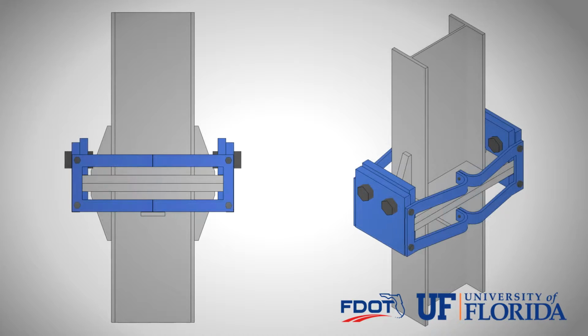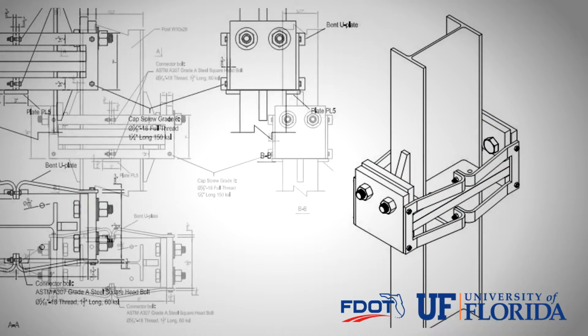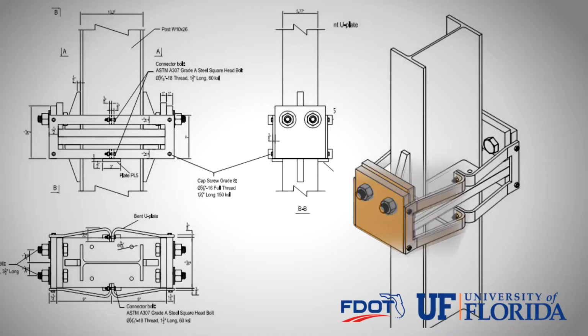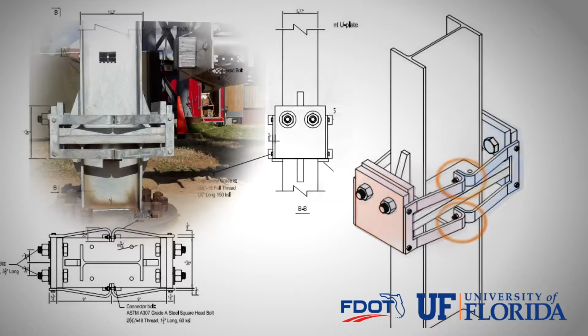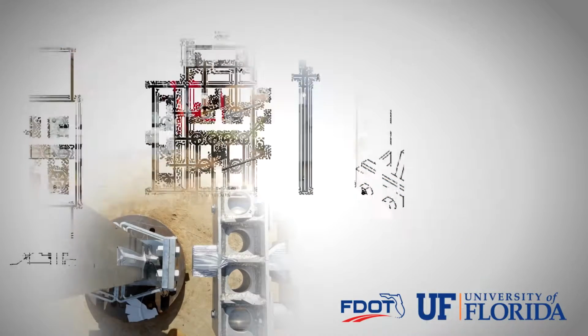The shear control moment collar is designed to clamp down on the breakaway system's flange plates and resist moments that develop as a result of wind loading on the upper post. The two collar halves are held together by 4 bolts, 2 on each side. These bolts fail in tension during impact loading.